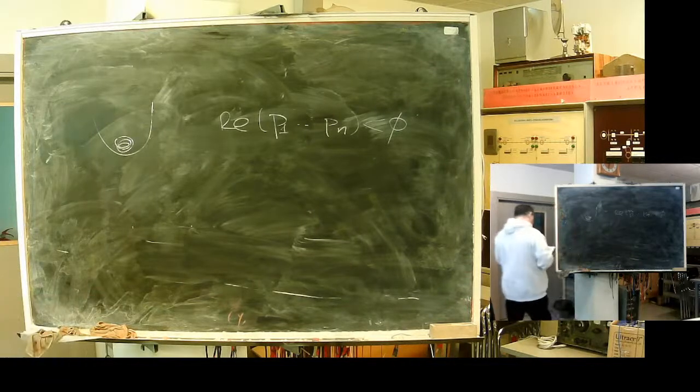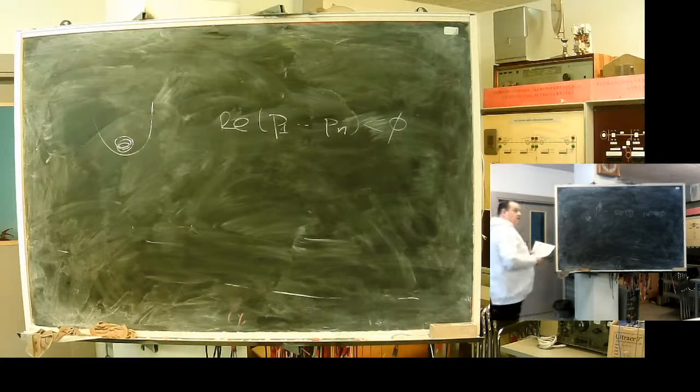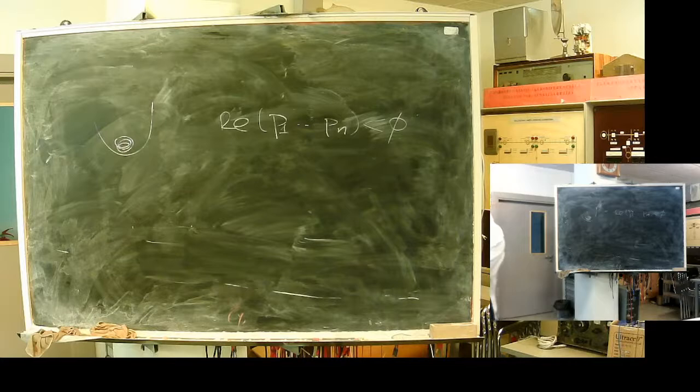It will not be stable. So only at that frequency, or each root, they can be real roots without imaginary part. If roots are real, the process goes like an exponent to the 0. If we have complex roots, they usually are conjugated, and they describe oscillation: their imaginary part describes the oscillation frequency, and the real part describes whether the process goes down or goes up.